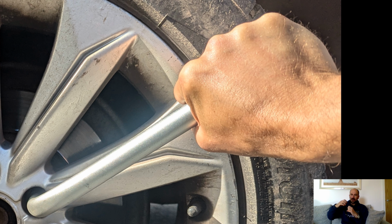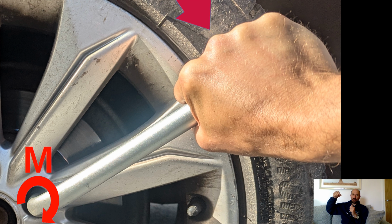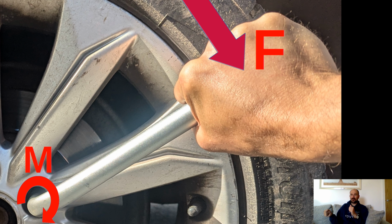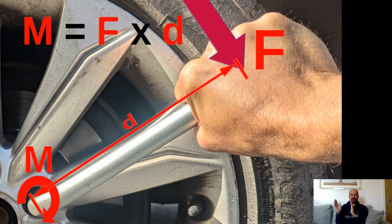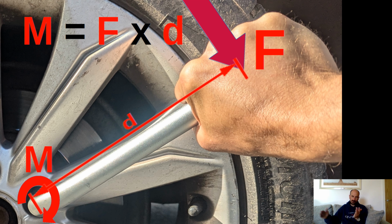You've got this twisting action around the bolt, and a force being applied to the end of the spanner. Now, the moment, the twisting around that nut, is the product, the multiplication of the distance away from that pivot and the amount of force being applied. So if you put more force on it, you get more twisting. If you use a longer spanner, so you have a bigger distance, you get more twisting.